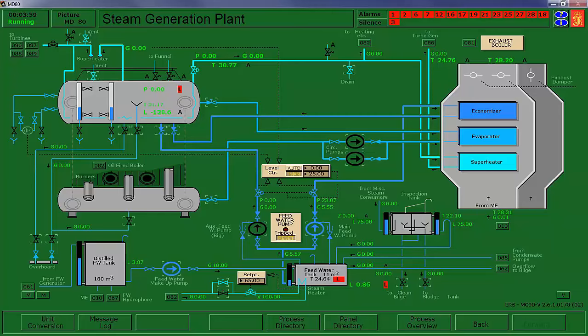In other words, that's low enough that as we start heating up this boiler, I'm going to worry about the swell, as we develop those steam bubbles, raising up the boiler water level too much. So my level in the beginning is going to rise. So we want it slightly low on light off. Now, normally where I stop is about 60, and then just right now, go ahead and shut it down. It'll drift up, and you'll see it drift up a bit.